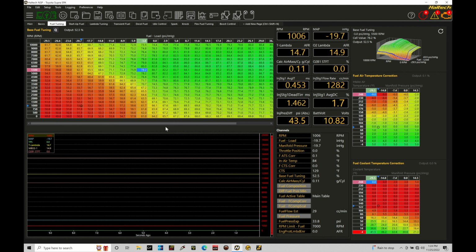Now, if we have everything sorted out in terms of our fuel modeling and our airflow modeling, the equation will balance, and essentially we're going to hit the target air fuel that we're requesting. So we like to always have both the fuel model and the airflow model dialed in properly. And we've talked about how to deal with bad injector data, how to tell if the values in our table here are accurate in the speed density model, and understanding how all of the injector data plays a role in changing that fuel mass to injector pulse width. So we've gone through everything pretty extensively.